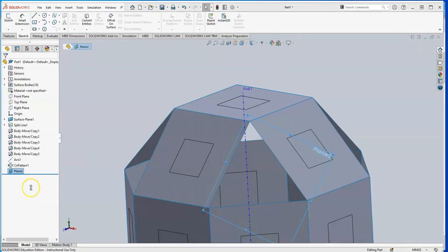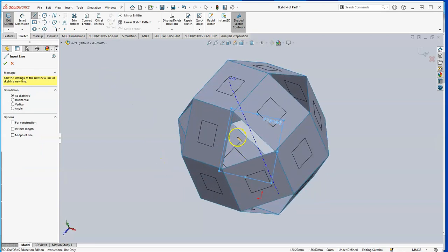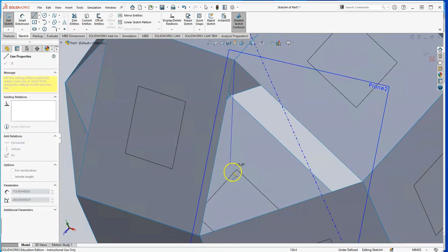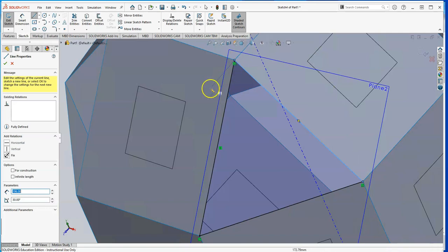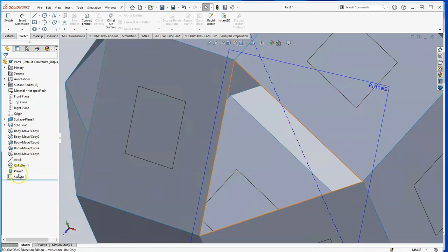Select that. Next, I want to create the triangle on that plane. So if I go to select plane 2 and sketch, and I want to create a line on that, reorient it so I can see my plane. And I select the vertices of the triangle as the endpoints of my lines. Back up to the starting point. Should have a closed sketch, press escape to stop that, and click this in the up here to create that sketch. So I have sketch 4 there.